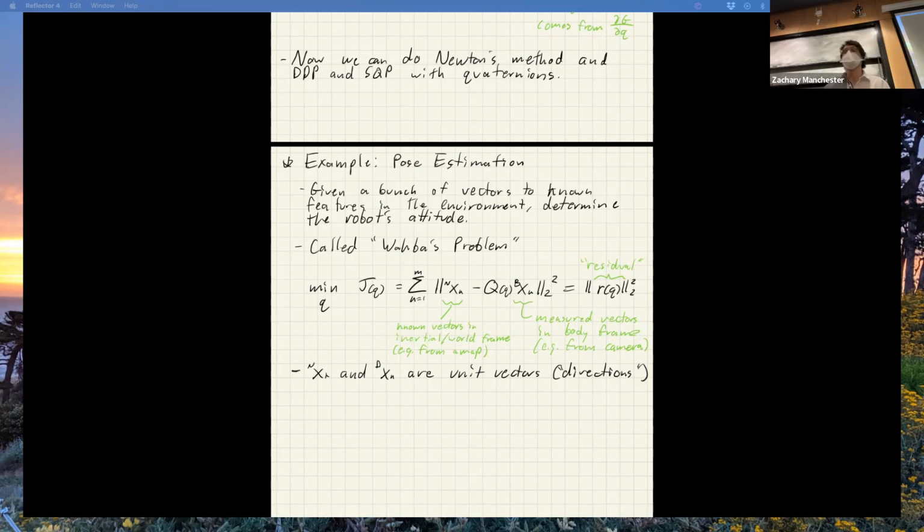So if that's the rotation matrix from the body frame to the inertial frame, right? That's how we've defined all this stuff. And we want to optimize the unit Quaternion here. So we're going to plug in there, we talked about how to convert a Quaternion to a rotation matrix. That's all we're doing. You could also write it down as the Quaternion matrix multiplication sandwich version of this, but yeah, that's it.